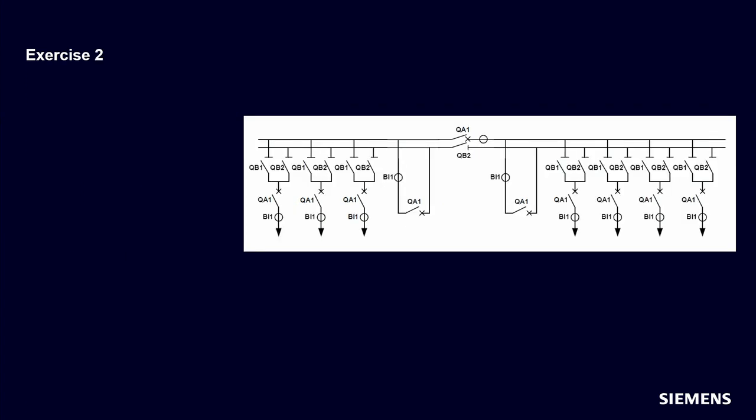Okay, now it will be interesting. How many will give here the answers correct? That's a double busbar. I see some couplers. And I see also sectionalizing couplers. I see a sectionalizing coupler. I see sectionalizing disconnectors. So first, how many bus zones do we need? I guess this hopefully is quite simple. It's 4. So 2 bus zones on the left side of the coupler and 2 bus zones on the right side of the coupler.